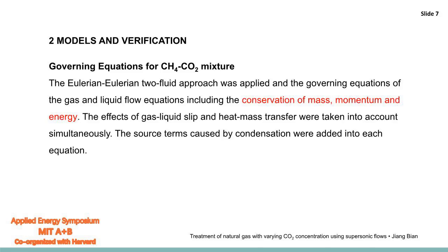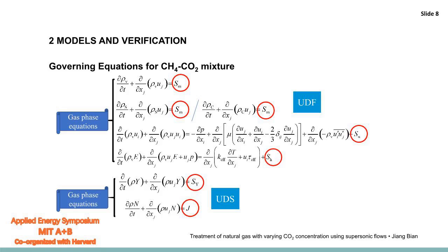The governing equations for the mixture, including the equations of mass, momentum, and energy, the droplet number density equation, and the relation between the droplet radius, droplet number, and liquefaction rate are employed to describe the liquid phase.